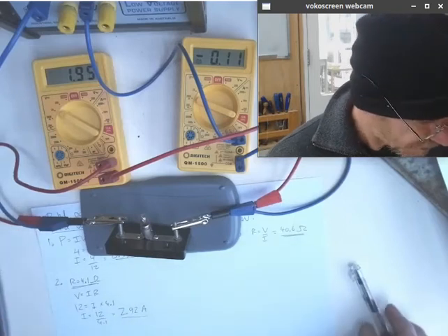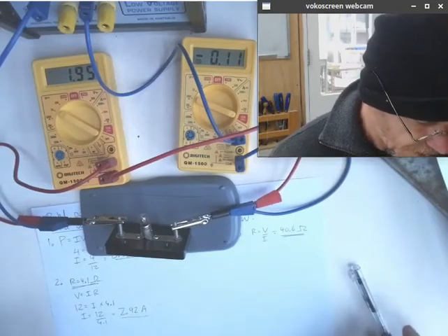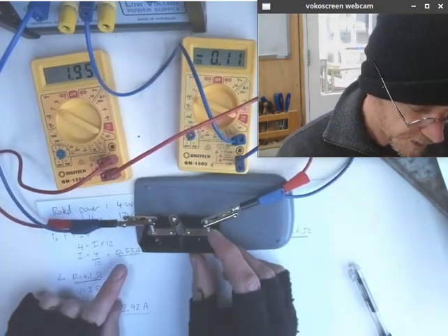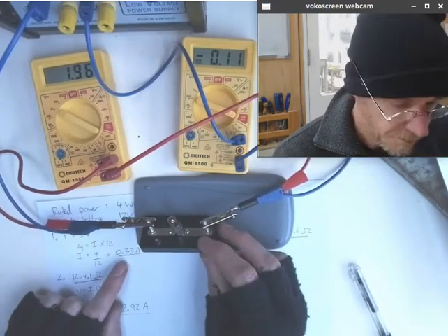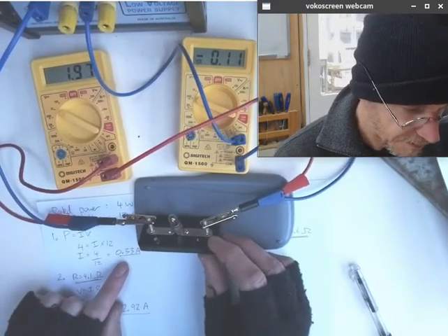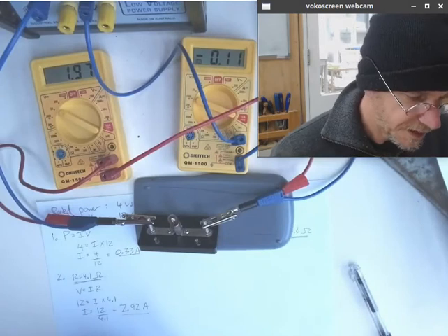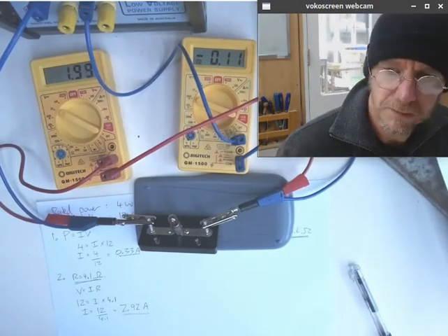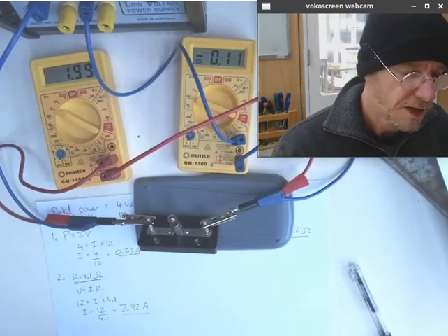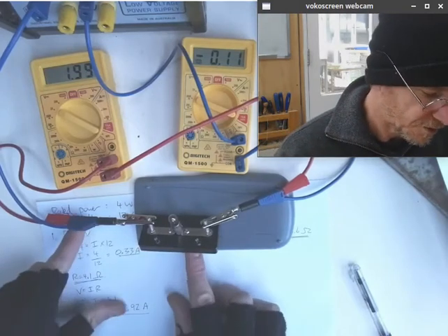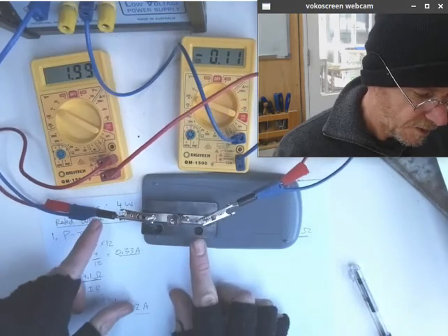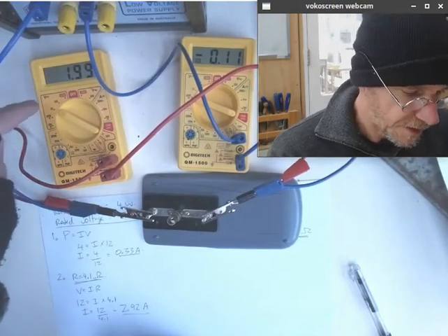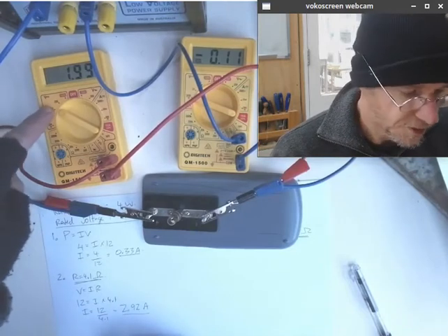So that is why, if we're trying to work out the predicted current for an item, how it's going to behave when we connect it in our household circuit, how it's going to contribute to the total current being drawn in our household circuit, we need to use the manufacturer's rated power or the rated current they provide on the appliance, not go taking our multimeter and measuring the resistance of the product.